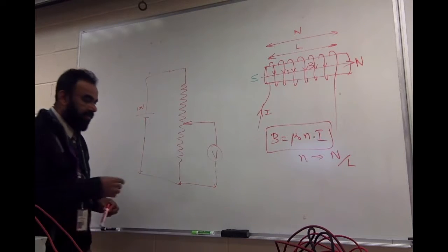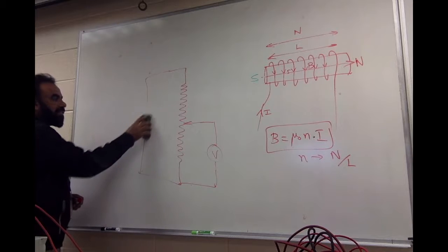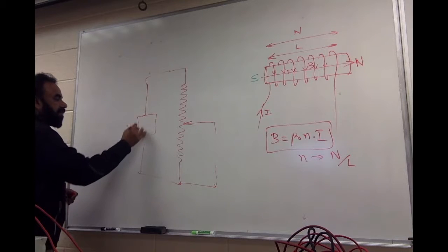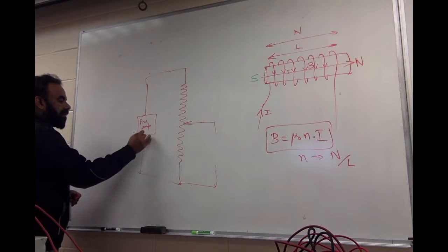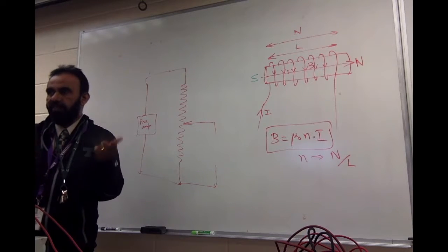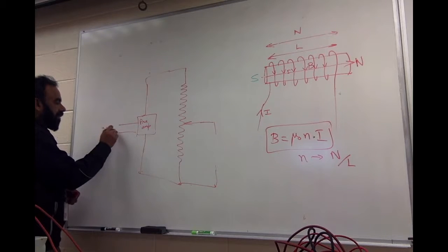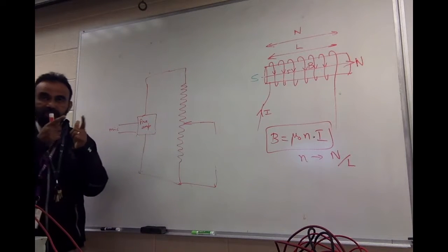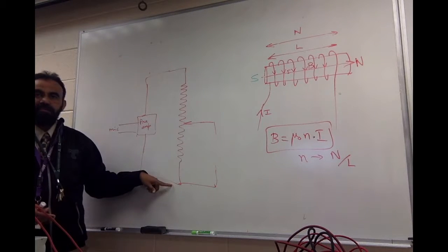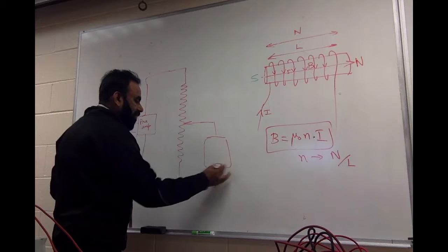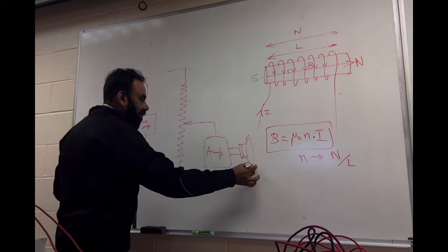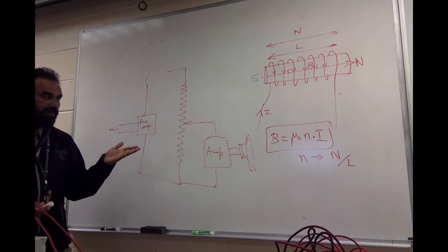Now, you can think of it as part of an amplifier. What is getting connected here is a preamplifier. A preamplifier is a circuit that does the first part of the magnification of the signal. What goes in is the microphone. So the microphone is the input, and the preamplifier will amplify it to some extent, and then it pushes here. Now this is supposed to go to the main amplifier, and the output from here goes to the speakers from the main amplifier.